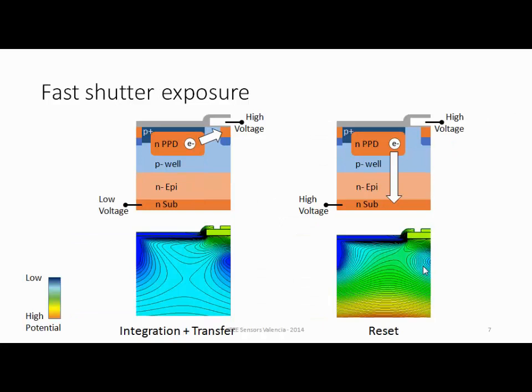So our solution was never to lower the transfer gate voltage during the imaging. The way we do it is just keep the transfer gate voltage high, and then the potential map of the photodiode looks like this. Every electron that arrives, or let's say every photon that arrives, creates an electron-hole pair, and the electron is immediately swept into the floating diffusion or VCCD area, the storage area. So it happens very quickly,